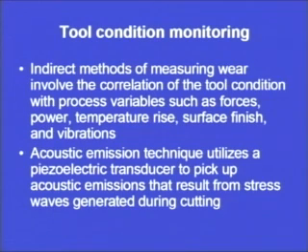So, one point is that we can directly measure the wear using a toolmaker's microscope, or we can measure it indirectly. We can keep a check on all these process variables and conclude whether tool wear has taken place or not. Then there is another technique called the acoustic emission technique, which utilizes a piezoelectric transducer to pick up acoustic emissions that result from the stress waves generated during cutting. These transducers pick up those stress waves and send a feedback signal that the tool is wearing. It may not be able to predict the rate at which the tool is wearing, but it can tell that tool wear is taking place.